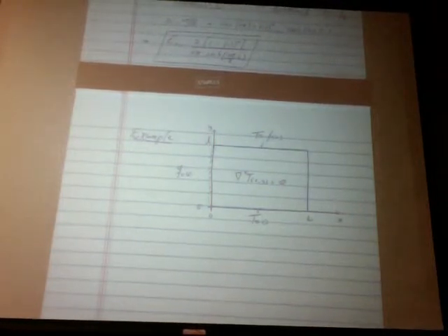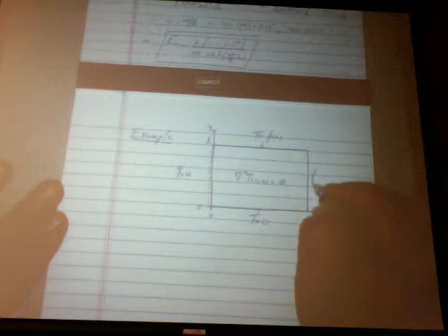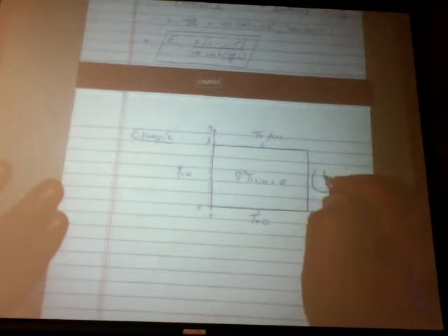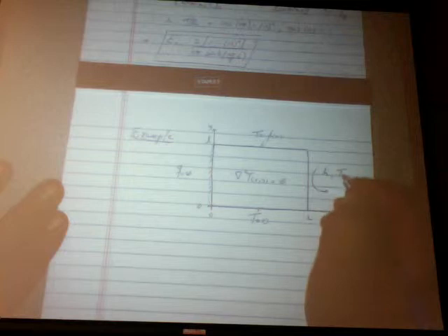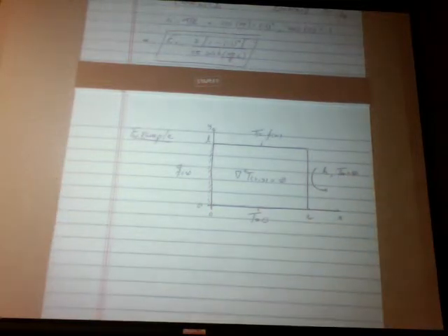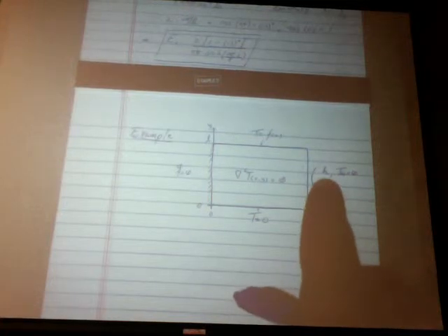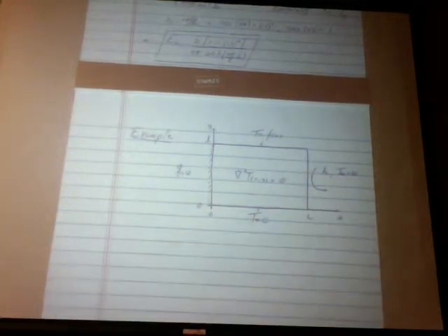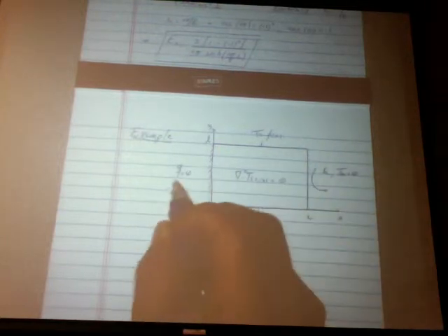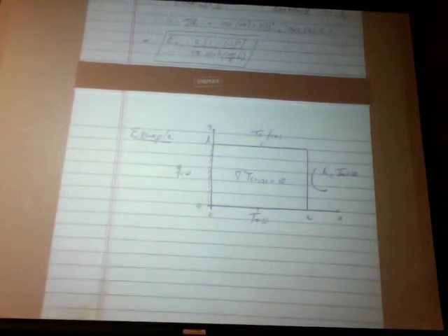We have an insulator. And then here, let's say that we have a flow coming in at h and T infinity. And let's make that T infinity equal to 0 to make it homogeneous. So we have a convective condition on the right-hand side because we have some sort of flow with a film coefficient h and a temperature of 0 circulating on the right-hand side. So we have a first kind condition, non-homogeneous, second kind, third kind condition, both of these homogeneous, because the value is 0, the value is 0. Okay? So how do we express that?